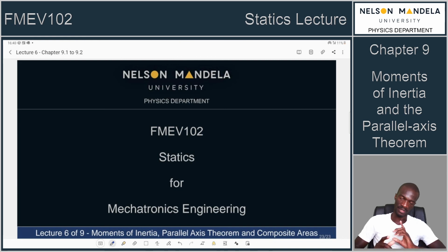So we need to grasp this concept of the moment of inertia. It is just a second moment. The moment of inertia is just a what? It's just a second moment. That second moment is calculated in the same way we calculated the first moment. But in this case, we have a distributed load. Because the distributed load has forces which have a value that depends on the height at which you measure them from some axis, we end up having to find the moment of a force that is distance dependent.